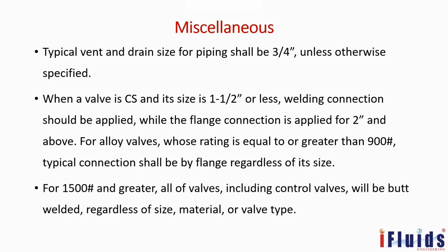Then typical vent and drain size of piping shall be 3/4 inch unless otherwise specified. Normally, by default, the vent and drain size of the piping shall be 3/4 inch. Otherwise, if the licensor specifically mentions something, then we have to change it.